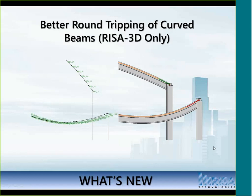Next, we've now improved the round tripping of curved beams. Now, this is for RISA 3D only. Bear in mind that RISA Floor doesn't currently support curved beams. But in RISA 3D now, if you have a curved beam that's present in Revit and you bring it into RISA 3D, we will automatically break that beam up into a series of segments. And then if you change anything, we'll just bring that back into Revit accordingly.